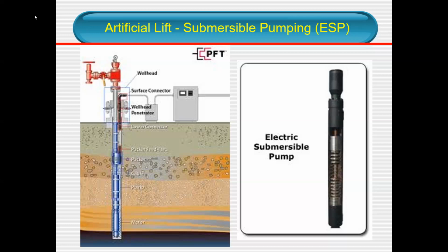We have also tried using chemicals to make sure that the unconsolidated becomes strong. This chemical goes into the reservoir, and it basically acts like a gum to attach all this sand together so that it doesn't flow. But at the same time, we must make sure that the pathway for crude oil to flow to the surface is not blocked. So while you are trying to do something, it can have a bad effect. So everything must be taken into account.